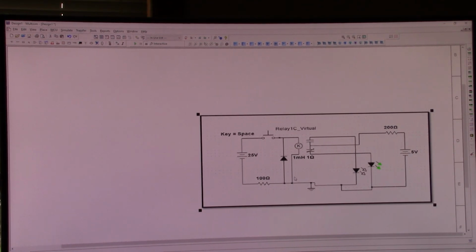so this relay has a couple of components that you might not be familiar with. One is this arrowhead looking thing. That's a diode, and the purpose of this diode is when this relay contact releases, there's a reverse voltage, and to stop that from damaging this power supply, we put a diode like this.